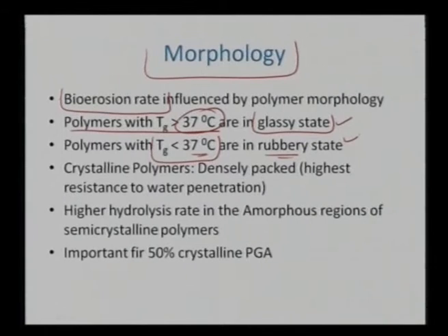So in certain cases the polymers can be either amorphous, crystalline or semi-crystalline. Crystalline polymers are very densely packed. Once they are densely packed, it becomes highly improbable that water can get very easily into the bulk of the material. So the crystalline polymers show the highest resistance to water penetration. So there is a combination of all this. First let us see only the crystalline polymers: they are densely packed, so they show very high resistance to water penetration.